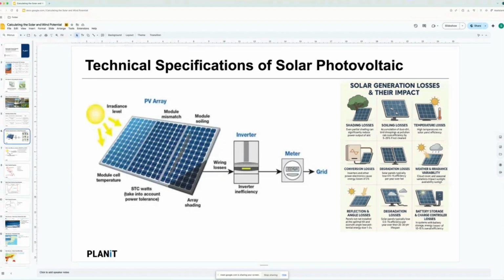But in practice, if you actually install solar panels in the Sahara or in the Middle Eastern area, the output is not going to be too different from a solar panel in Germany. Germany is not really a sunshine country, but even with strong sunshine in the Middle East, the output is not going to be too different. Why? Because dust covers the solar panel, and in the end you have less electricity output from the panel. It's a very practical reason.